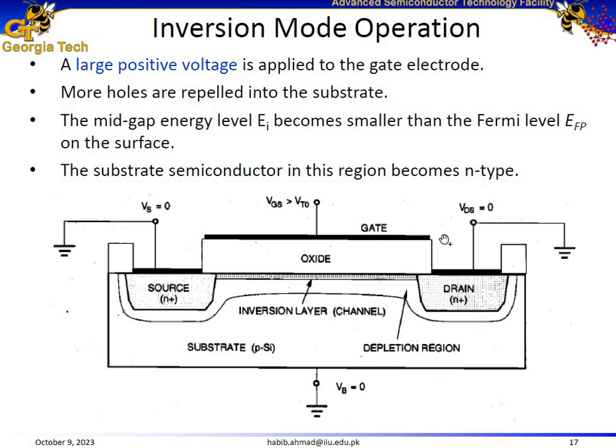First, as we can see over here, we have a metal gate or polysilicon gate, and then we form a channel of electrons for an n-type MOSFET. So basically we have two conducting regions, and these two conducting regions sandwich a dielectric, an oxide, silicon dioxide. So it acts as a parallel plate capacitor. This is one kind of capacitance in a MOSFET.